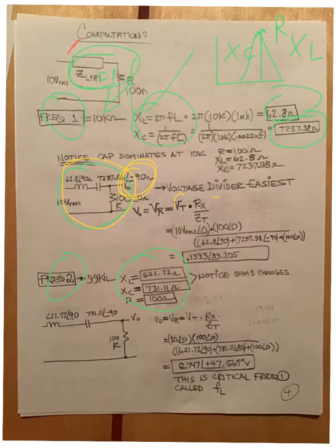If I plug in the impedance that's situated down here in yellow, up here at the top, I put it in as a big rectangular circuit. Just add it all up in rectangular, because this is a series circuit. You see the impedance can be done in polar and it can be done in rectangular. I chose to show you that I could convert them very quickly into polar, but we could have left them in rectangular. It just would have made the line a lot longer, including the I factors and the magnitudes.